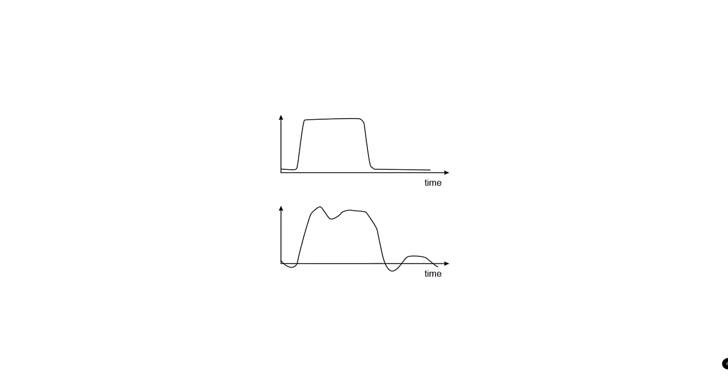The clock signal, like all signals, is analog. We require the clock to be of high quality with only small deviations from its ideal waveform. Imperfections in the clock signal can come from many sources. The resistance, capacitance, and inductance of the clock wiring and associated circuits can introduce delay into signal transitions as well as noise. These circuit elements can also couple to other signals in the clock, injecting crosstalk that distorts the clock signal. Electronic phenomena can also introduce random noise.